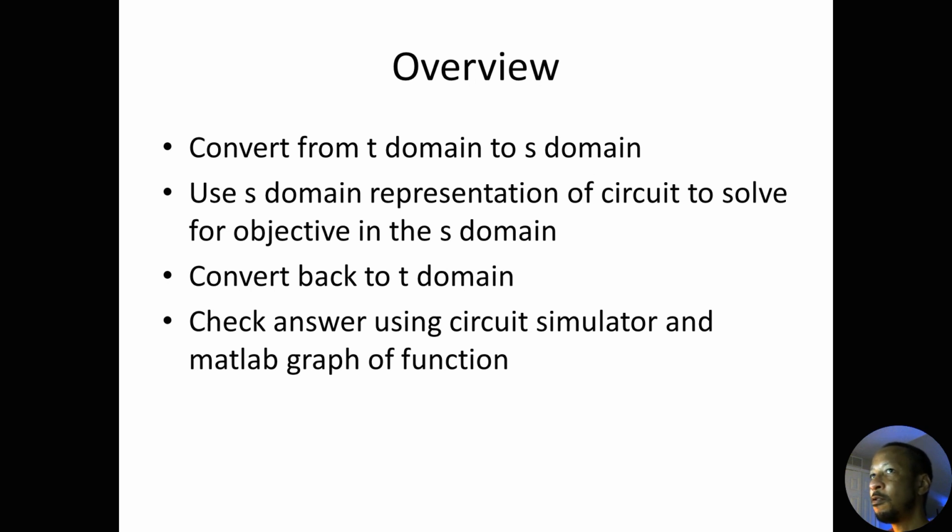First, I'm going to convert from the T domain to the S domain. That's what you always do when you start out these types of analysis. Then I'm going to use the S domain representation of the circuit to solve for the objective in the S domain, whatever your T domain objective is, once you form that equation.